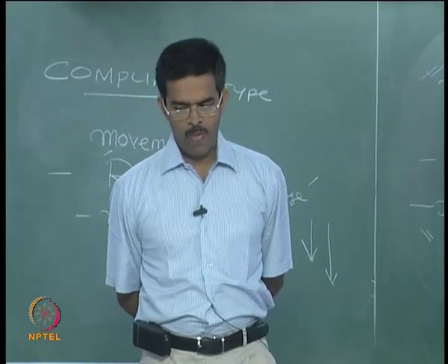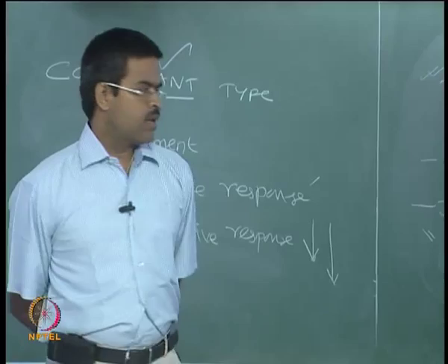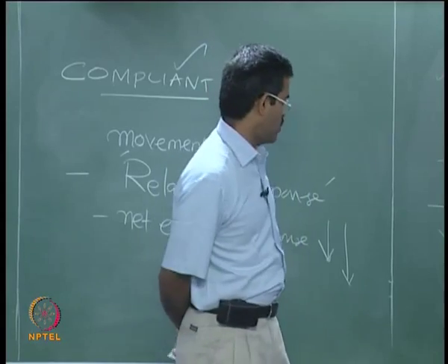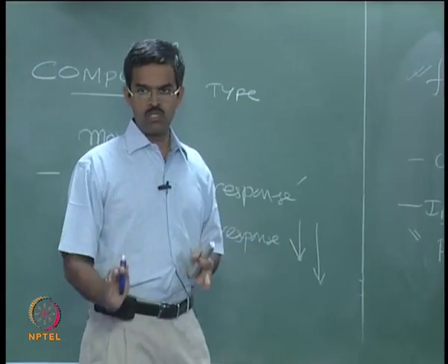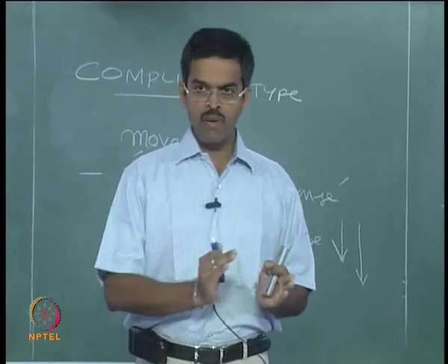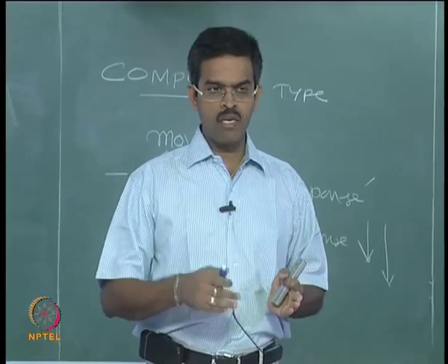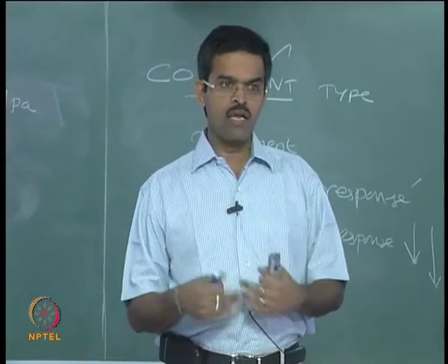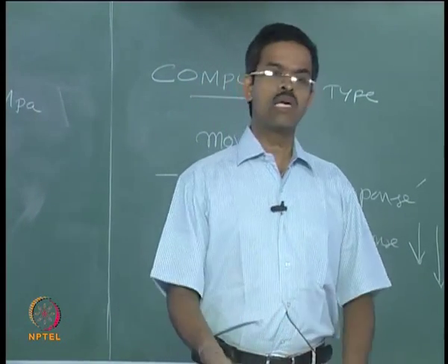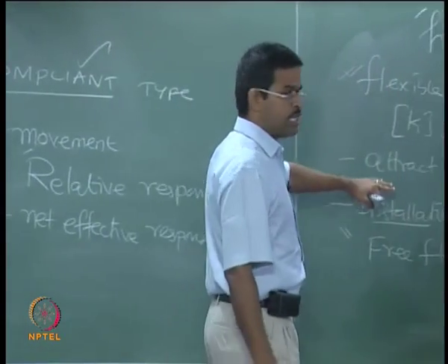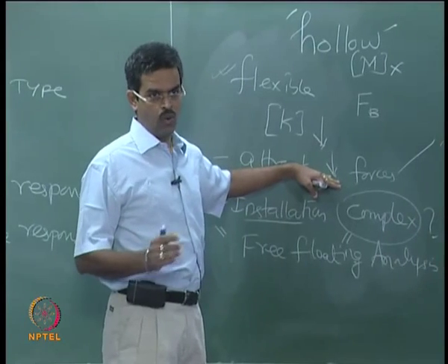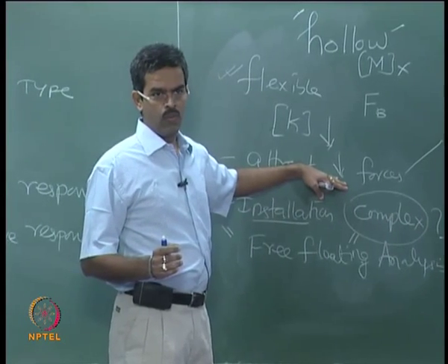Fatigue. Cyclic rotation. See, we will just clarify what the gentleman said. He says fatigue is an important item where I am focusing, therefore I want to reduce forces. Remember, interestingly, fatigue is a problem associated with a force of lower magnitude, but in repeated number of cycles. I am talking about the cyclic loading. The magnitude is not a concern in fatigue loading at all. Therefore, I cannot speak about the magnitude of reduction which will result in fatigue. No, that may not be the right answer.